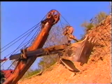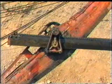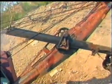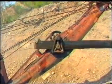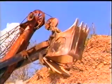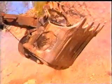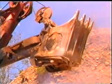The boom is a massive beam hinged to the deck at the boom foot, which extends diagonally upward. The dipper stick slides back and forth through the saddle block attached to the beam. Its lower end carries the dipper. It's a steel box open at the top and closed at the bottom with a hinged door. Its cutting edge enables penetration into earth.